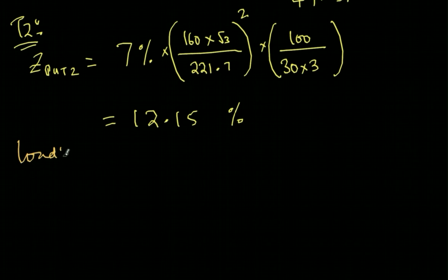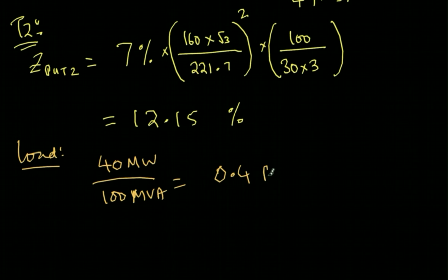So load: 40 megawatt by S base, that is 100 MVA. Because the voltage ratings are the same, I don't have to consider that. So this is 0.4 per unit at 0.9 power factor lag. So this is the load. This is actually active power.